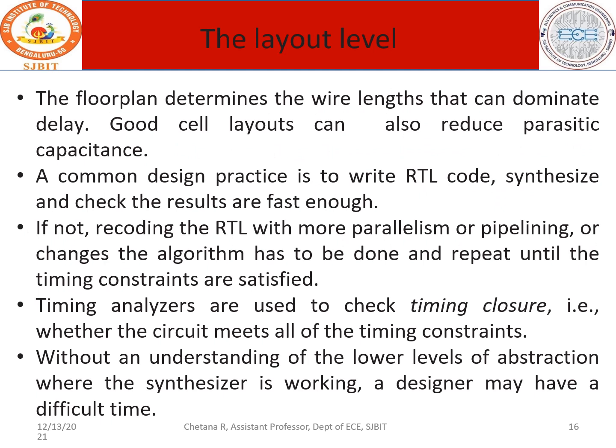Next, the layout level. After your design is done, it's the layout. What do you come across in the layout? The thickness of the wires and the spacing and all such things. It is the floor plan which determines the wire lengths that can dominate delay. So when you have the floor plan of the layout, you know how much wire it is going to consume. If you have good cell layouts, there can be a reduction in parasitic capacitance. Parasitic capacitance, as the name suggests, is an unwanted capacitance that has to be removed.